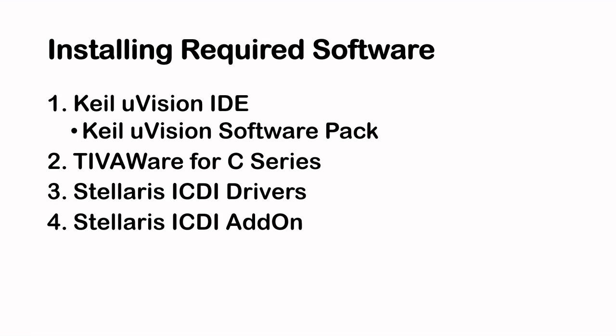Software. Installing requires software. Now in this section of the video, we're going to look at installing the Keil Microvision IDE and also the Keil Microvision software pack. Then we need to look at how to install TivaWare for C series, and then installing Stellaris ICDI drivers, and then finally Stellaris ICDI AddOn.